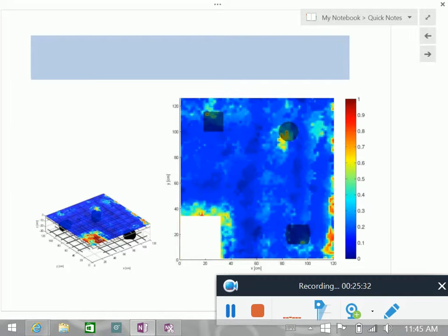So when you have impact echo, this is the edge of the slab. The problem is if you are very close to the edge, this is also acting as another boundary. So you are going to see some sort of a peak coming from that. The worst part is when your distance to this edge and your distance to the thickness is equal.